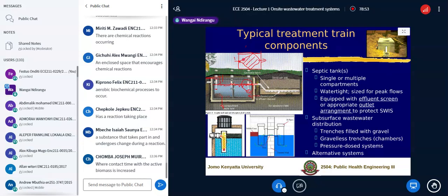Now, that is your effective area. We call these areas here, this one here, dead corners. Meaning that there is no reason for water to come from here and spread out this way. It will not spread that way. So it moves this way and moves that way. Water doesn't move like that. It moves in the path of least resistance. So effectively, as you can see, half of your tank's plan area is not effective.